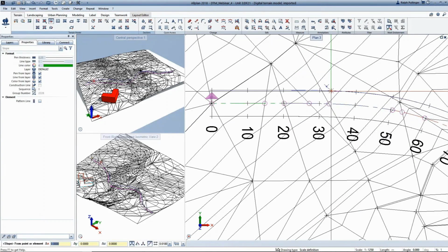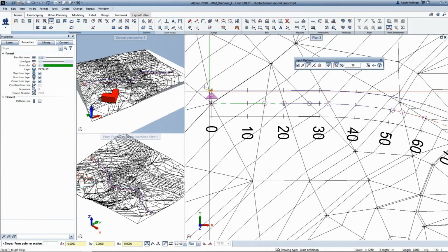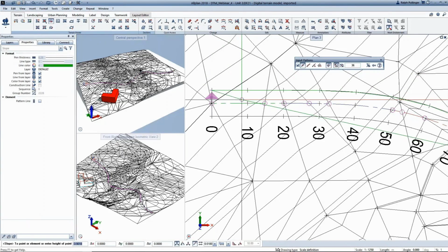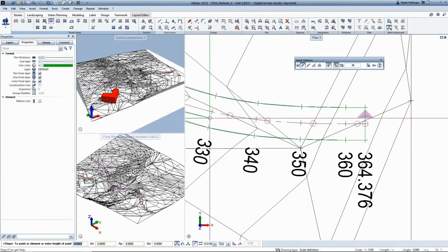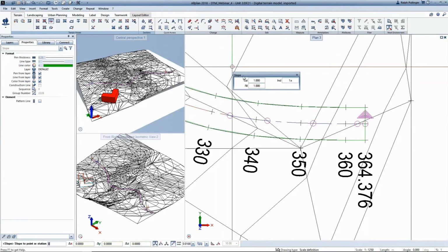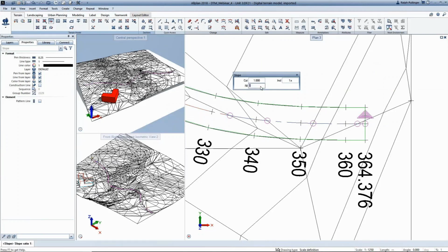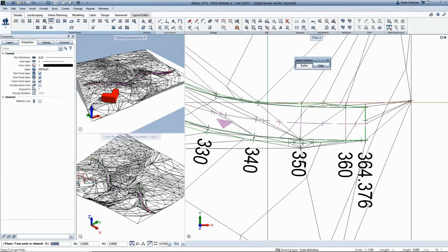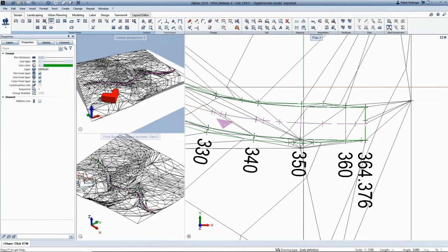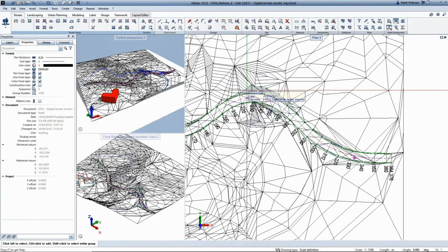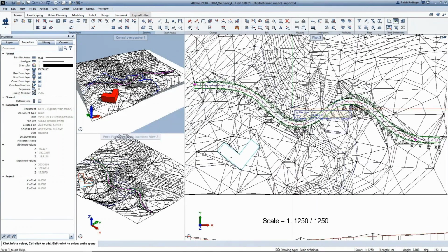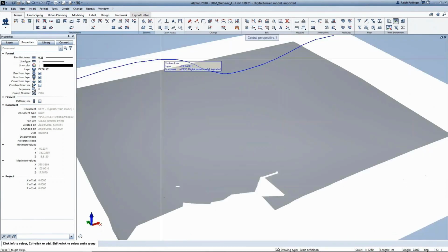So now what we want to do is look at our generated offsets, which could be the front or back or higher up if it was a retaining wall, for instance. And we're going to want to integrate this now into our design. So we can take the surface that we've just developed and we can tell it some profiles for cut and for fill, and we can project those slopes, as it were, into the model and integrate some design surfaces with the original surface.